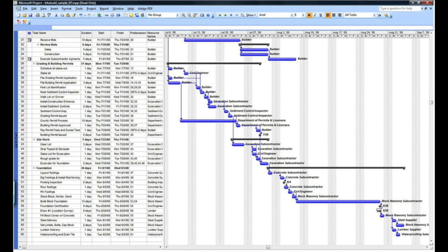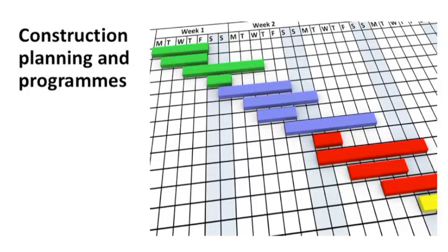Activity schedules, or Gantt charts, named after Henry Gantt, an American engineer, are often used in order to show when each item is required. It separates each item of work and includes resources and materials so that they are available at the correct time. New developments mean that Gantt charts can be linked to the BIM model. This is often referred to as 4D BIM.